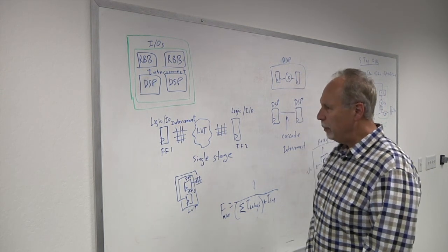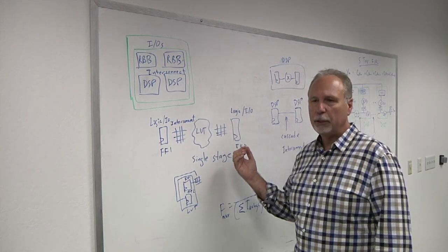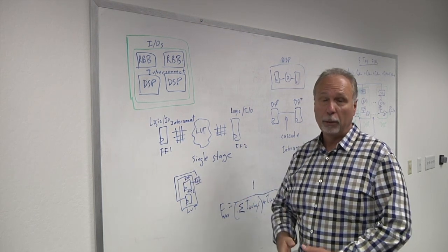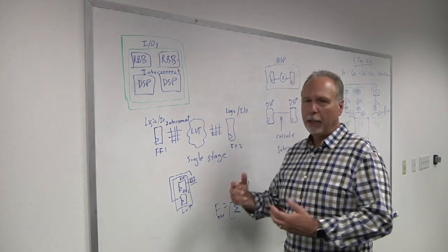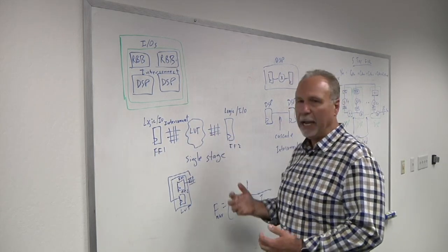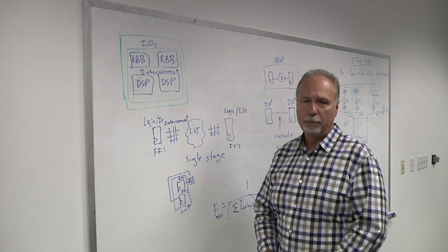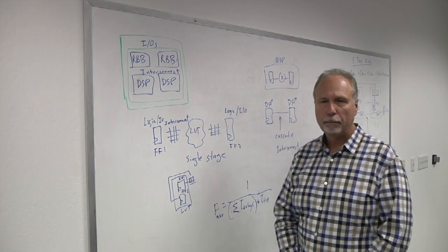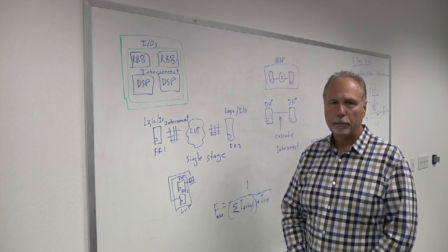The interconnect fabric is to be able to connect one logic element to another logic element. So it's equivalent to, in the ASIC world, a wire. In an ASIC, you would have a flip-flop going through some gates to another flip-flop, and you would connect that through a wire. In an FPGA, that interconnect is actually a fabric, which is either mesh or maybe some kind of hierarchical interconnect. The problem with wires as we get into some of the advanced nodes is they're getting very thin. Does this interconnect mesh improve the performance because of that?